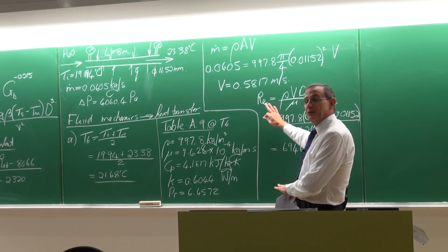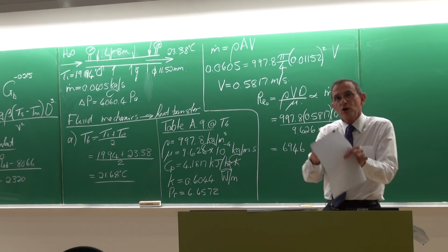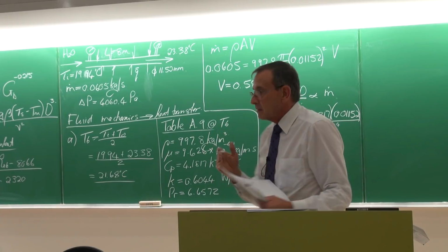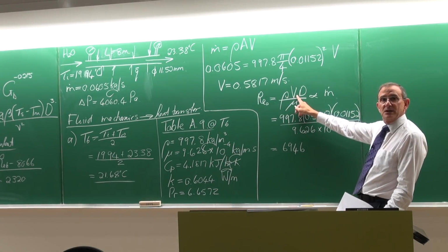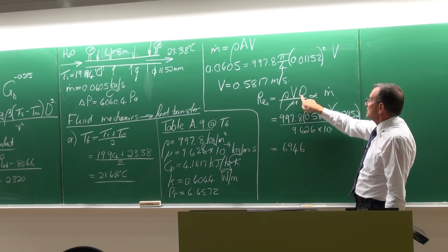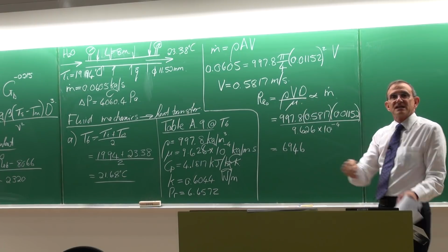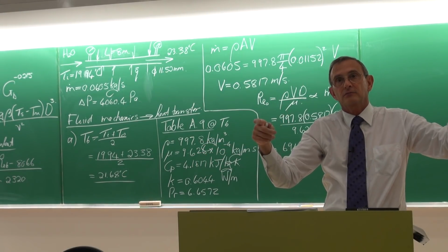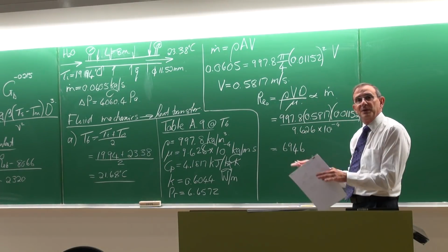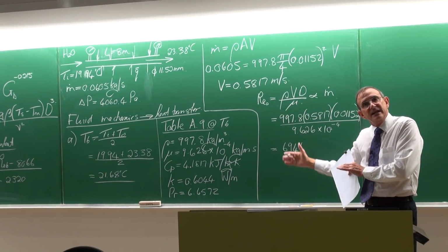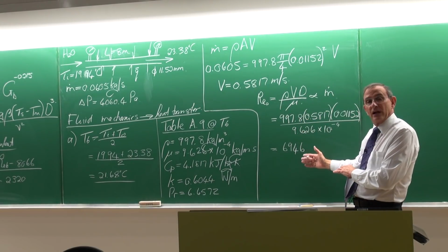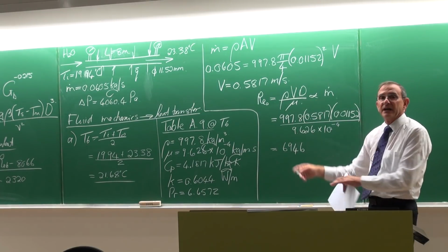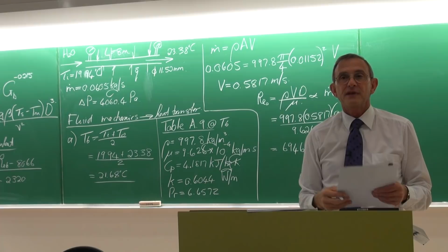You get to the same problem when you get to a car. Let's suppose you've got a Ferrari and you want to calculate the Reynolds number over this Ferrari. The equation is easy: the density, the velocity, multiplied by a characteristic length, and the viscosity. But now the question is, what do you use as the characteristic length? Do you use the length of the Ferrari, the height, or the width? People doing the experiments would typically see which one has the biggest effect, and the data would then be based on how that calculation was done. So we are moving towards the Moody chart, where the decision was specifically taken to use the diameter d in terms of the Reynolds number.